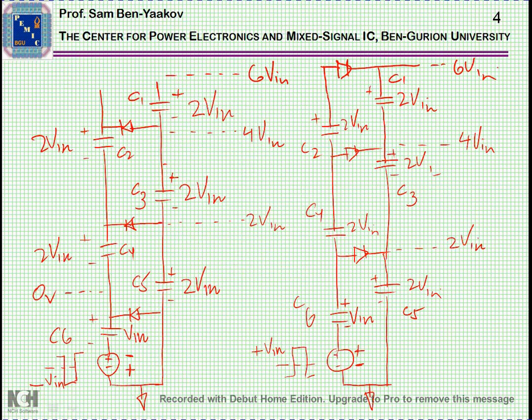Now, in the steady state, current will be drawn here, and the circuit goes on pumping charge to the capacitors, which are draining the charge to the load. We can now have a different look at what is really happening here by watching the operations that go on in the positive half cycle and negative half cycle.